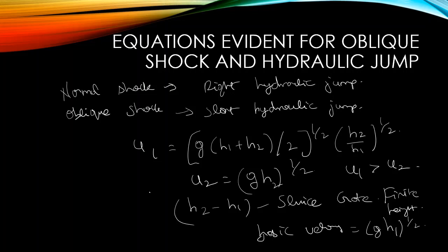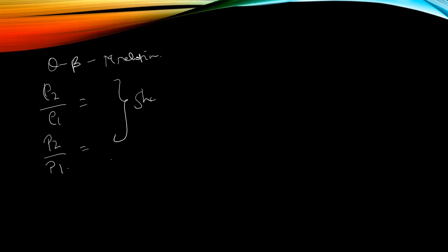And then what are the equations considered for this particular model? The equations considered for oblique shock relations, you may know very well, are the theta-beta-M relation, the rho 2 by rho 1 relation, and the p2 by p1 relation, right? You know all these relations from shock tables, right?